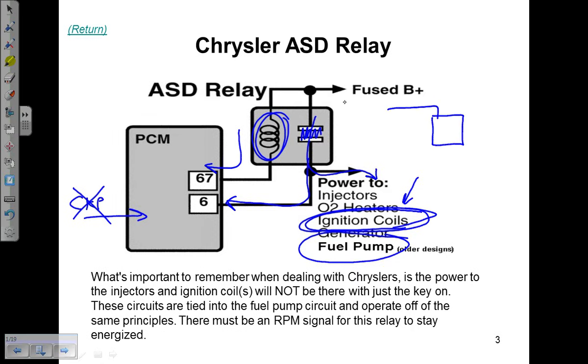ignition coil is our main power coming in. This one going to the computer to control the ground, the control side. This would be your power side. This would be your control. That you got 0 volts on your feed to your ignition coil. Cranking the engine over and you still have 0 volts on that ignition coil and you have no spark.